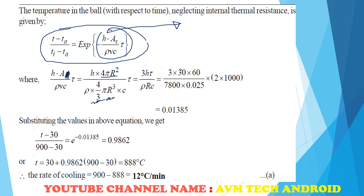We know the h value, we know tau, that is time, we know density, we know the radius r, and the specific heat. So everything which is required is available. From that we get hAs divided by rho Vc into tau value as 0.01385. So we have to find out what the temperature is.